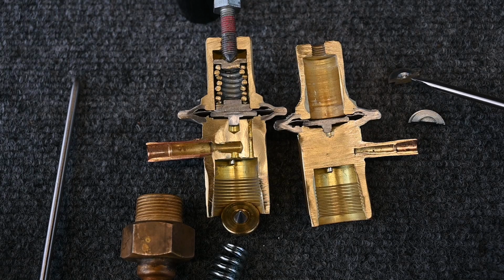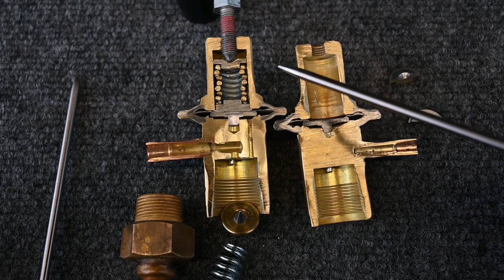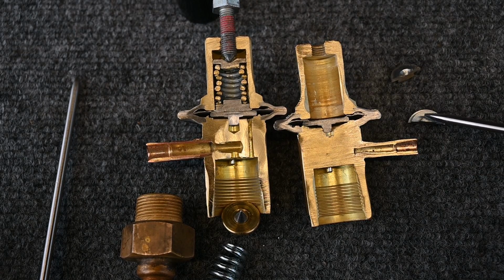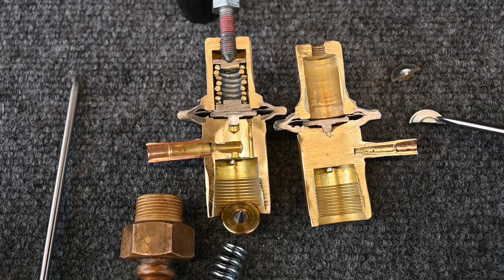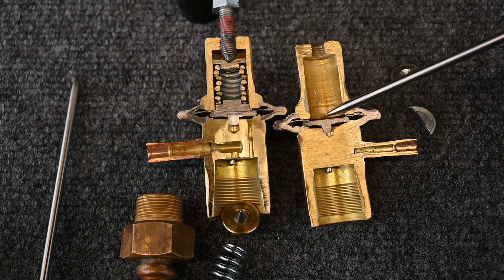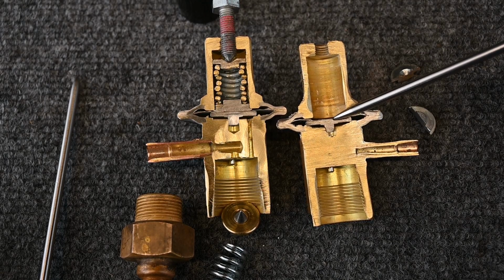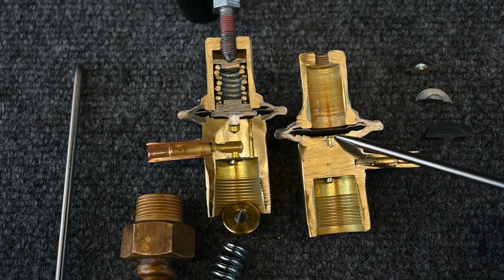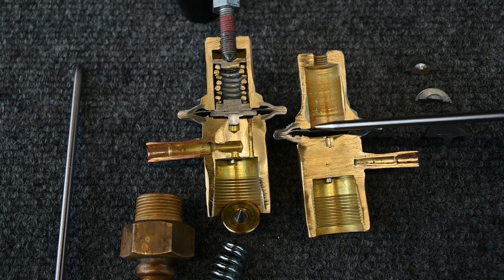So here you can see the top of the spring, it has this groove in it. That's where the top of this bolt pushes down, adding spring pressure. The other side of the spring fits right around this piece here. And on the bottom, we see that it's completely flat. That flat spot fits against a very fine piece of metal here, but we can't see it until we take this piece out.